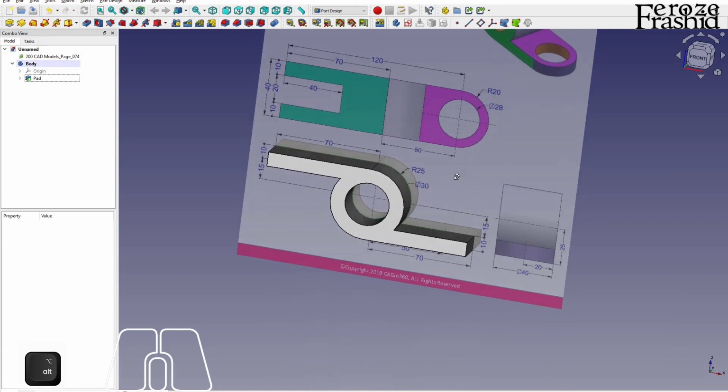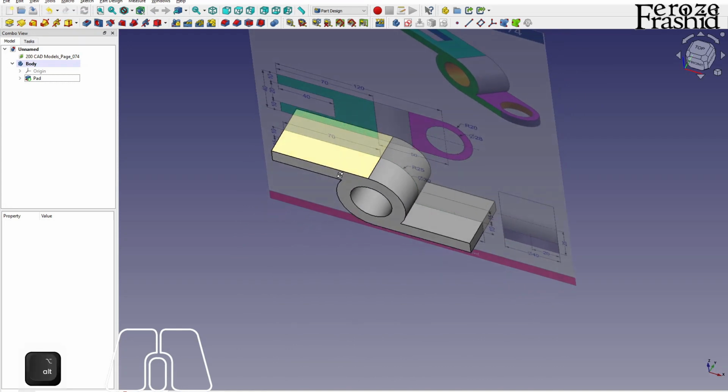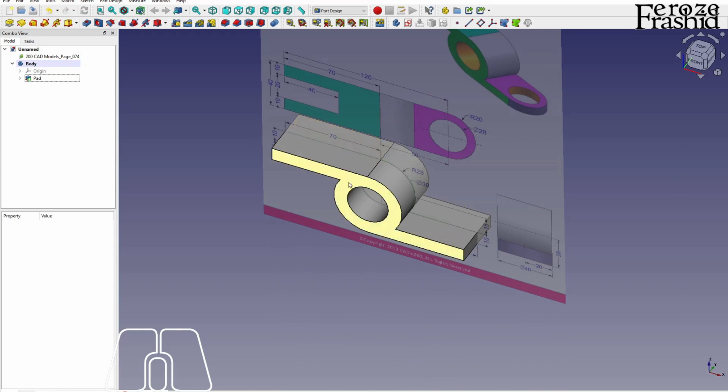Now we have to do some more finesse, final touching. One of them is to make this notch in the middle, which should be easier. So this is the XY plane. Now this is the XZ plane. This is the XY plane. This is the YZ plane. On the XY plane, I want to make a notch and I want to make a hole. I want to make these two round corners.